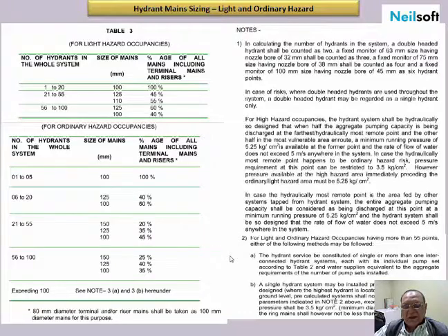For further details and more explanatory notes, you can go through this part of the notes. But most of the notes we have already discussed, like having the residual pressure of the hydrant. Those are given as 3.5 kg per centimeter square. And at many places we have actually discussed it. And the pressure also required for the light hazard 5.25, and for the ordinary hazard 7 bar or 5.2 bar, already discussed and to be followed.